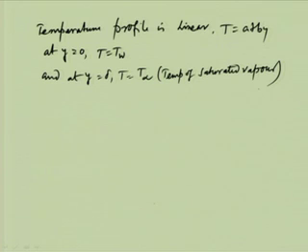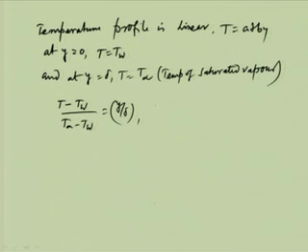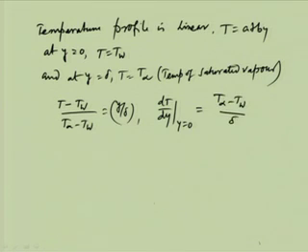Okay. Under that situation, if we put these boundary conditions, we get (T minus T w) by (T infinity minus T w) equals y by delta. This is the linear temperature profile. So, this is an assumption, and then if we try to find the expression for del T by del y, dT by dy at y equal to 0 becomes (T infinity minus T w) by delta. Okay.